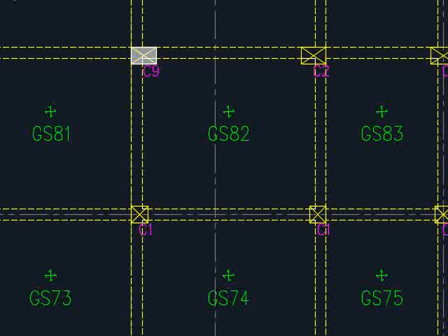First, you analyze the load acting on each column. Based on the loads you analyze, you classify them in accordance with a range. Maybe you put them in ascending order, and then decide how many classifications of the columns you're going to have, and classify accordingly.